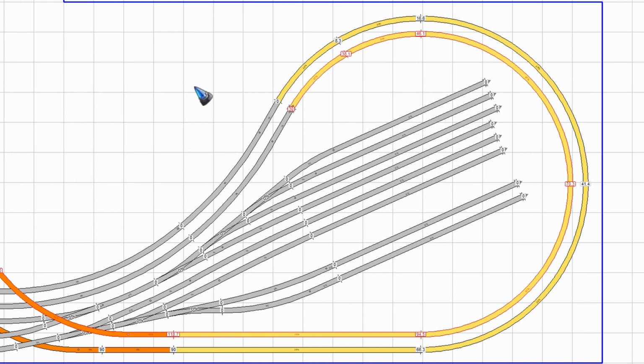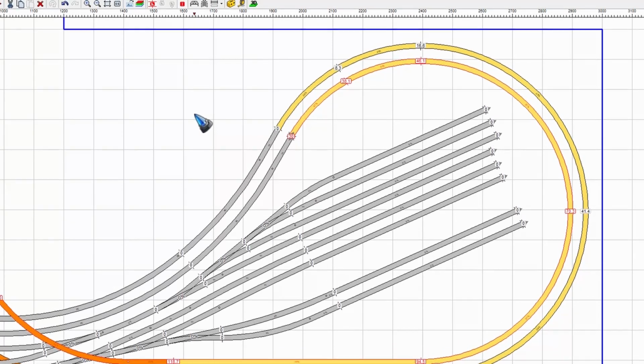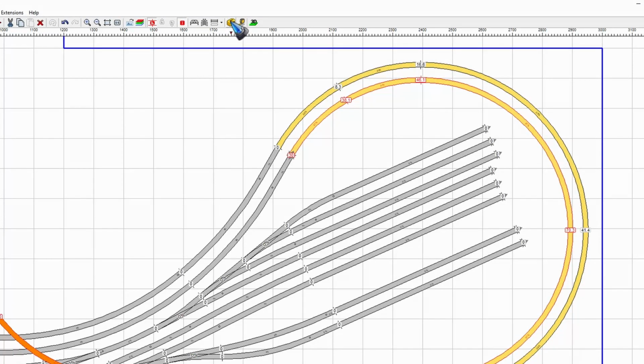There's also another way to shift the height of a selection, and that is by using the toolbox. In the toolbox, the drop down has a height shift function. We can enter a number, let's say 5 millimeters, and now we can hit a button increase or decrease, and that will change the entire selection.